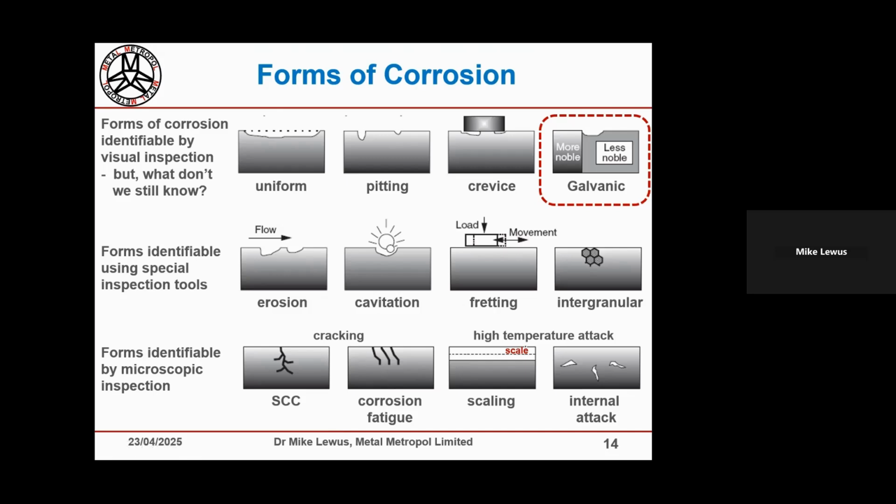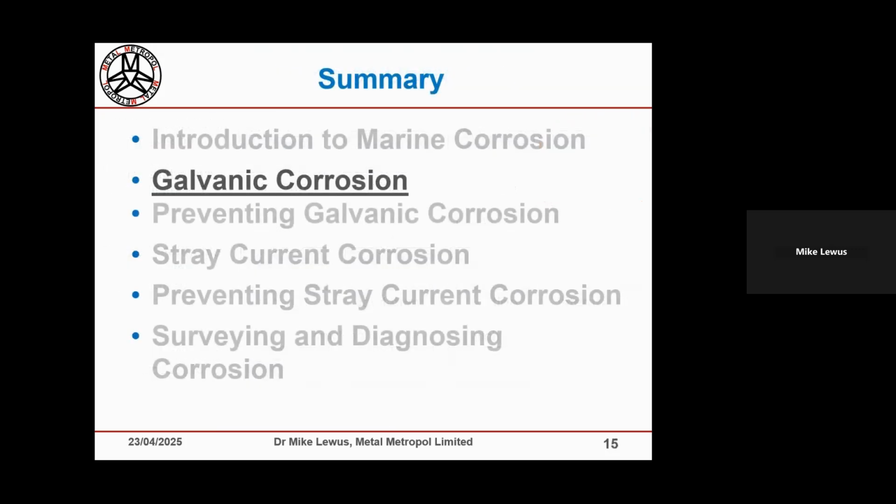And how are you going to answer questions like, has the cracking got to a level of severity where we've really got to do some serious maintenance or replace parts? Even things covered by scale and corrosion debris, by looking, you're not going to know how much thickness is left of the component, whether that's hull plates, ship plate, or some other component. So I know visual inspection is the first step, but it falls short of sometimes telling you all the crucial things that you need to know.